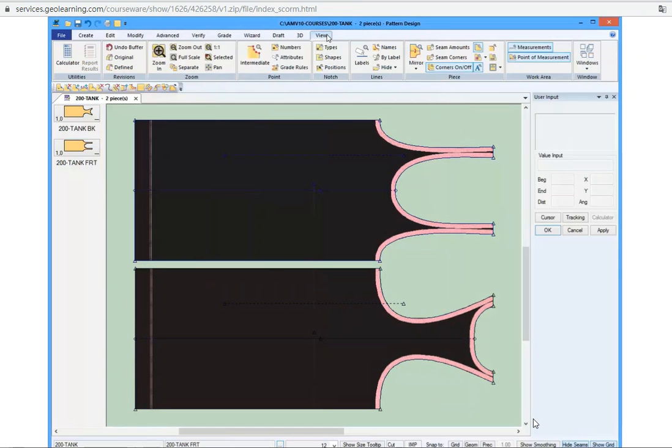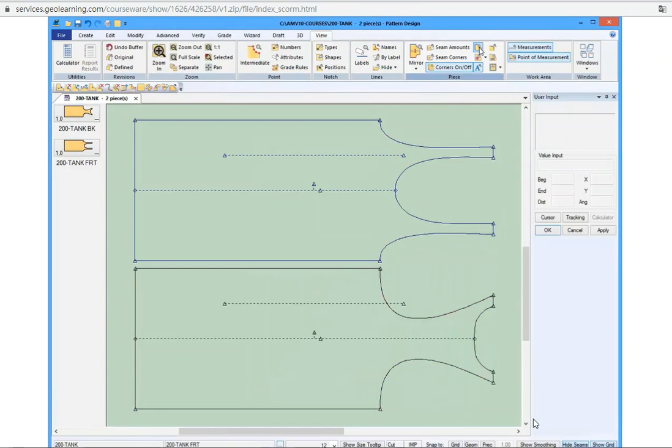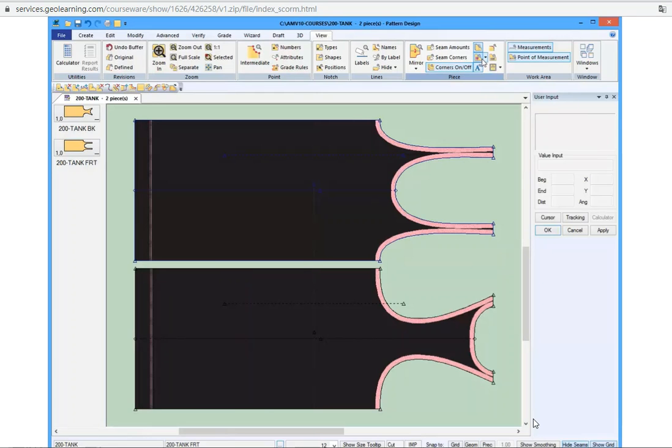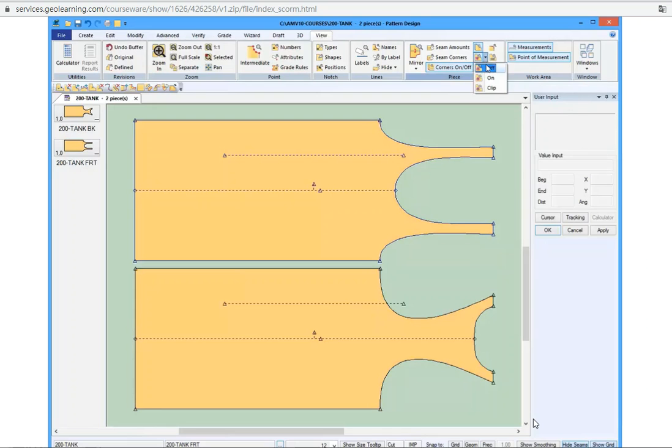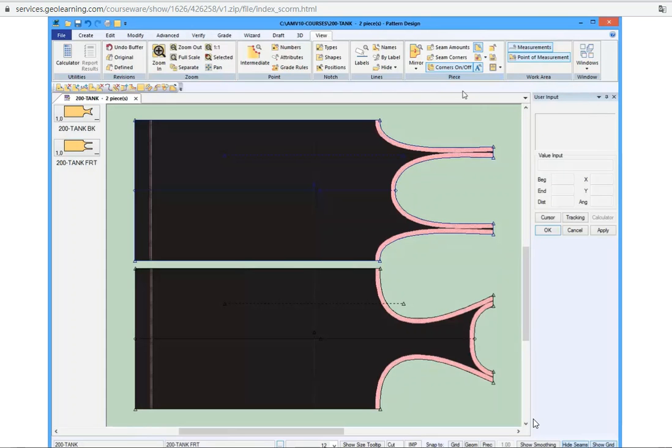In this example, we see that the fabric images are automatically turned on for the displayed pieces. There are two more options found in the View tab menu, which control options for viewing fabric fills. Filled pieces will turn the fill for the piece on or off, whether it is a fabric image or a simple color fill. Fabric Trim Edge controls whether the fabric, trim, and edge images will be viewed. In order for fabric images to be viewed, both options must be toggled on.